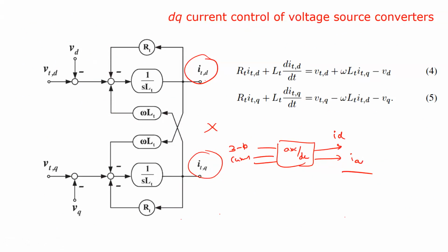Right. So no need to measure or do all these things. And moreover, when you're not measuring the currents, the values depend on these parameters. So if you accurately know the value of this coupling resistance or coupling parameter, then only the accuracy will be maintained. For example, if there is some deviation, the actual inductance is 1 millihenry, but somehow you kept 0.9 millihenry, then the difference will affect the grid side currents or the inverter currents.